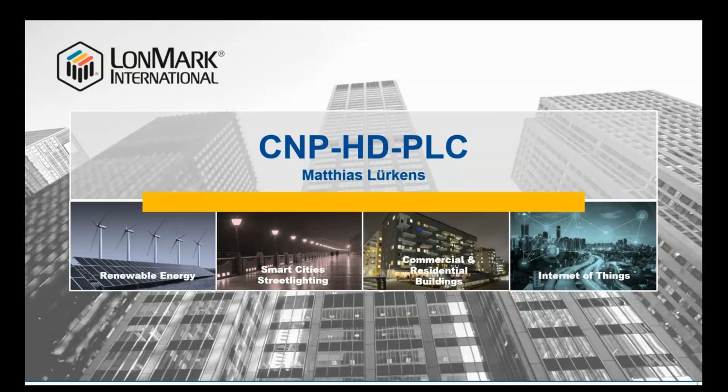In my presentation, I will talk about the basics. So how do we use HD-PLC for LON? You see here that I wrote CNP, which means Control Network Protocol. That's the magic terminology from the international standards like ANSI CTA 709 or ISO IEC 14908. In a standard you cannot write LON, so in that case it is the Control Network Protocol.